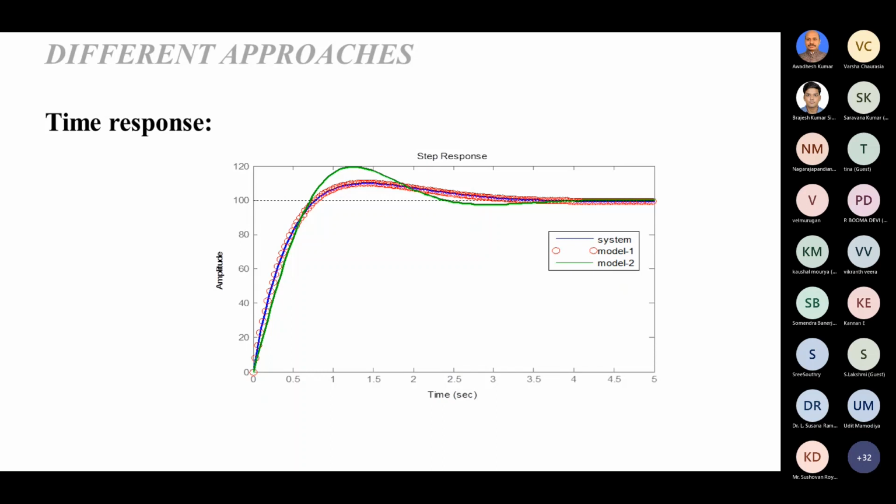In fact, in earlier research, the Padé approximation sometimes gave better approximation. People find that even if we are not including Markov parameters, and are including only time moments, the overall time response is better. Initial matching is also better, and the steady state matching is also better. So then they tried to calculate the time moments and Markov parameters of the system and models. They found that in certain cases, even though only the time moments are matched, the Markov parameters are automatically matched. So only by matching time moments we are able to get matching of Markov parameters itself.